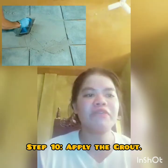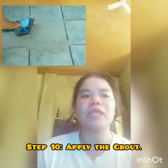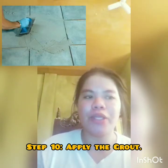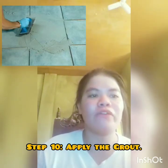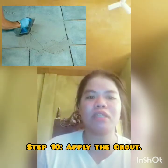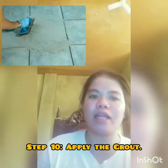Grout is available in a variety of textures and colors. Pick a color that matches the color of the tile. Use a rubber trowel or float to spread the grout across the tile at an angle to be certain to get it between each tile.